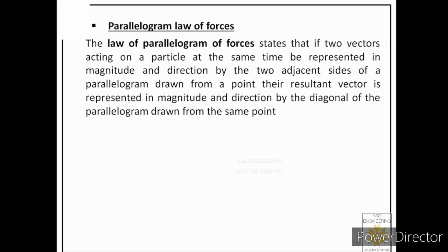Let us first see its definition. The law of parallelogram of forces states that if two vectors acting on a particle at the same time be represented in magnitude and direction by the two adjacent sides of a parallelogram drawn from a point, their resultant vector is represented in magnitude and direction by the diagonal of the parallelogram drawn from the same point.